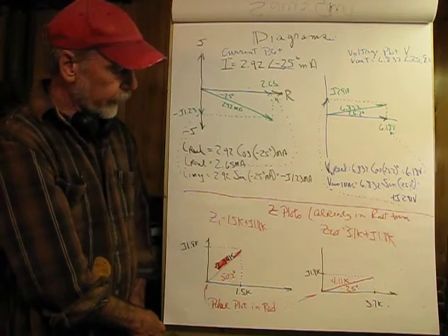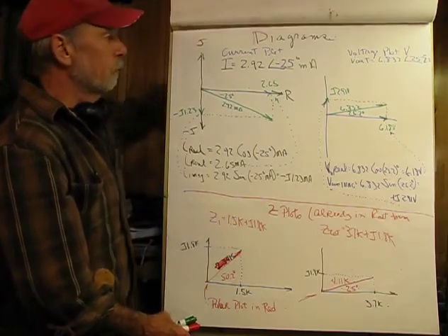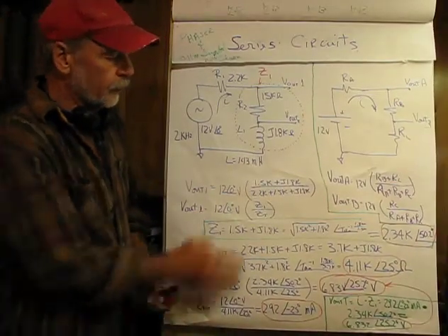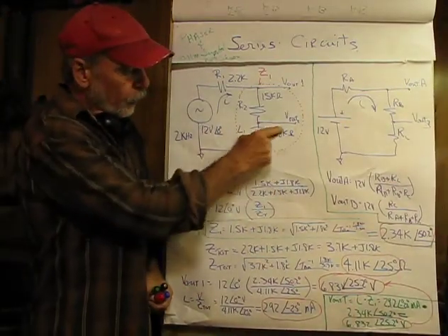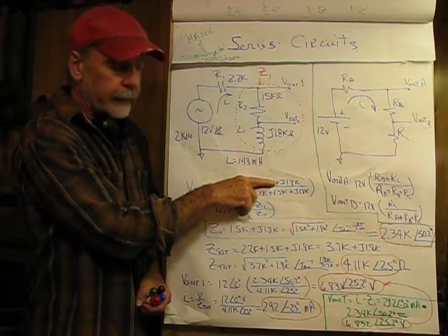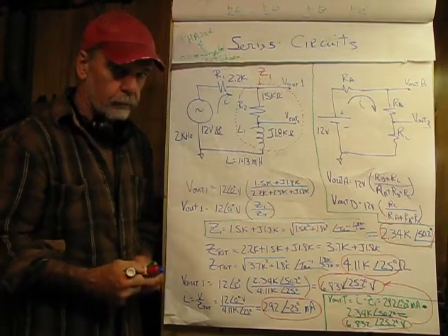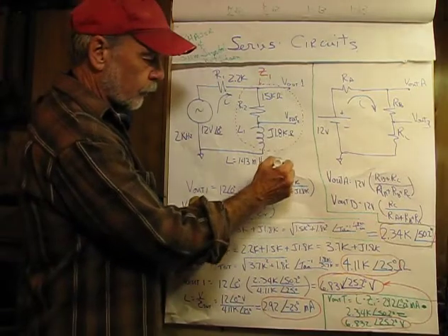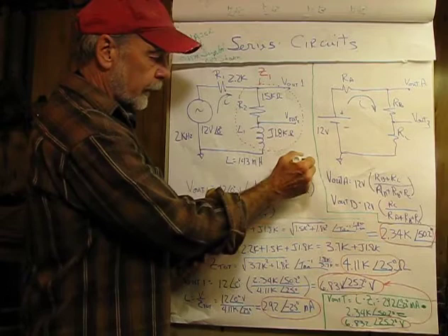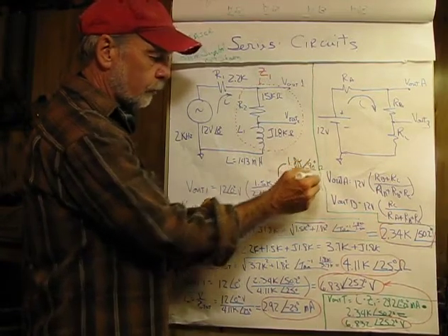So we could go on to find our second output here. I haven't done it. Really would just kind of be a repeat. It would set up the same way, except if I wanted V out 2 in the numerator, the only thing I would have would be J 1.8K, and when you convert this into polar form for the division, just remember this is going to be 1.8K at an angle of positive 90 degrees ohms.